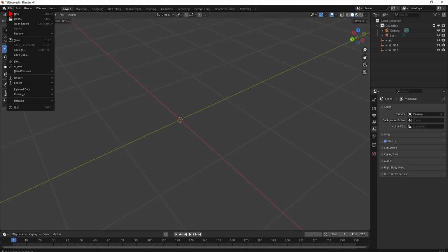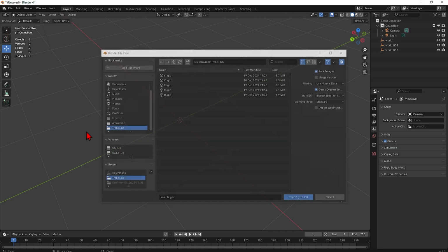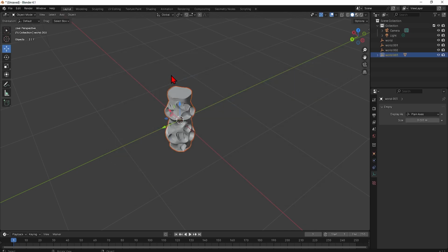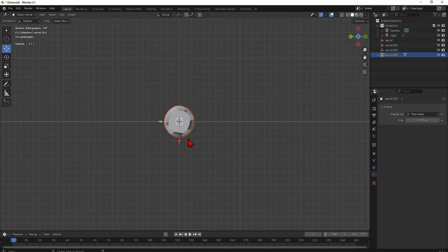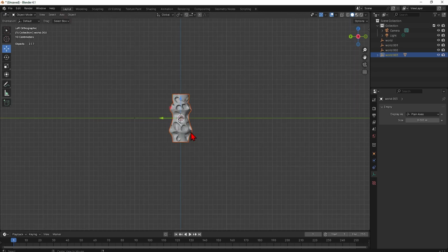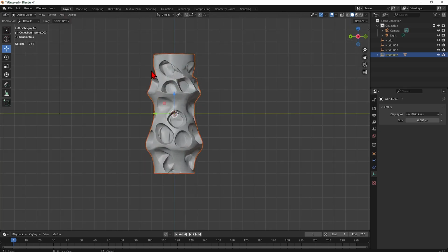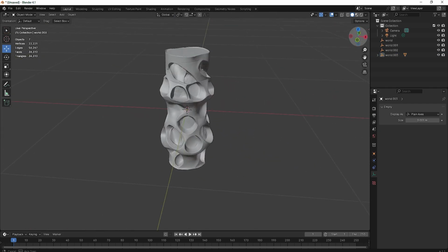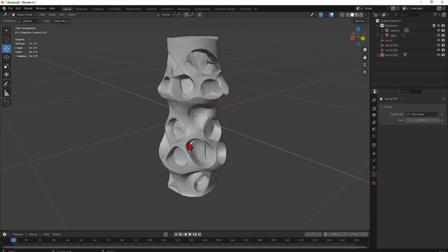In Blender, go to File, Import, and you can see the GLB file here. It will load the one that we just generated. You can see that this mesh is far from perfect and could be retopologized using more advanced tools in Blender, 3ds Max, or even AI tools, particularly useful for close-up detailed assets. I will show you some quicker methods instead, since I won't be using these models for close-ups. Both smoothing the edges and merging close vertices will suffice.